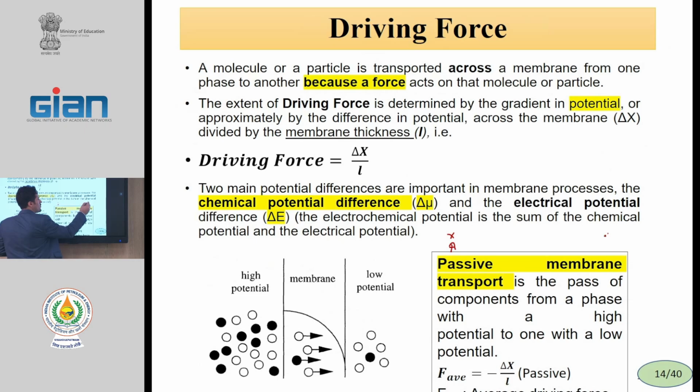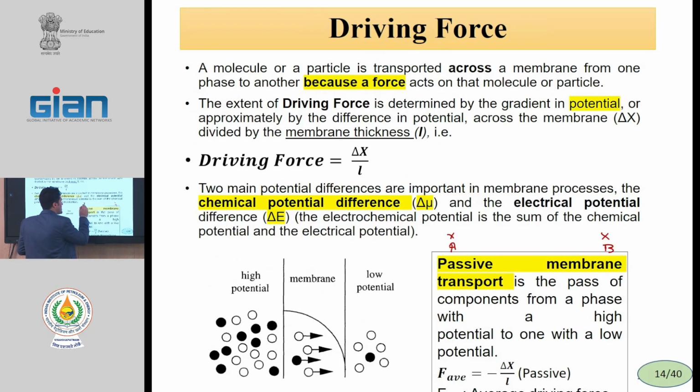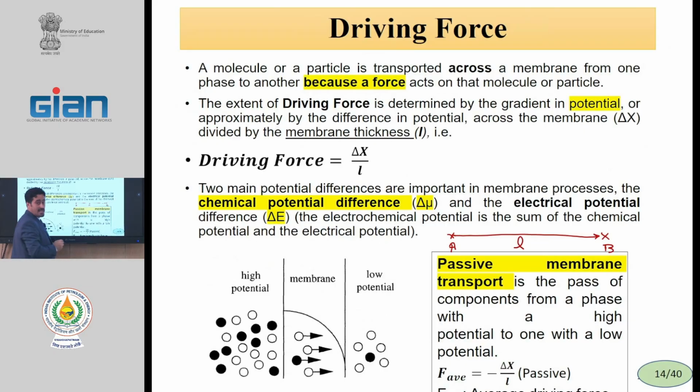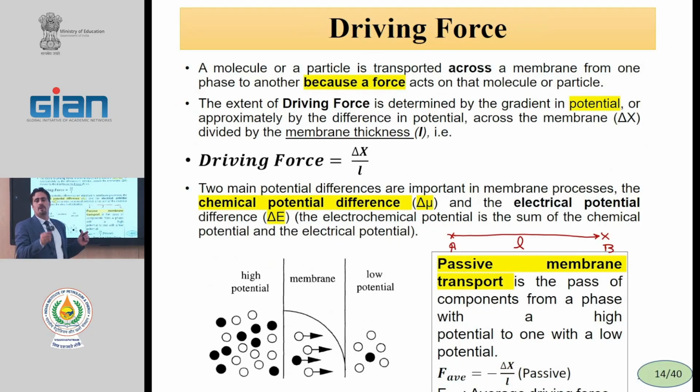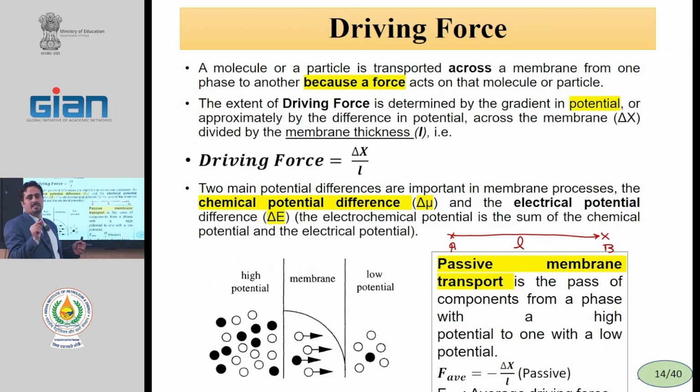From A to B in mass transfer, the distance is important. This distance is L. In membrane science, this distance is the membrane thickness. Therefore, if we fabricate a thinner membrane, the flux will be increased. Therefore, we must prepare 100 micrometer membranes because the flux is very important in membrane separation.